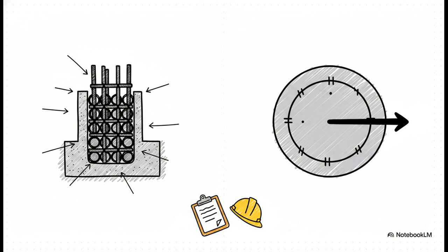And the difference in how these fail is massive. If a section without compression steel fails, you'll see large cracks forming at the bottom as the material stretches. But if compression steel fails, usually due to overloading or really common installation errors like improper spacing or inadequate concrete cover, you will witness explosive spalling. That's where chunks of concrete violently break off, and you can physically see the steel rebars buckling. It's a nightmare scenario. Identifying these variables isn't just textbook theory. It's about preventing catastrophic buckling on your watch.